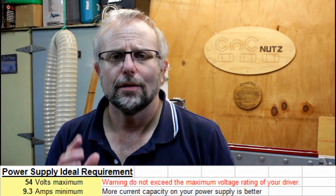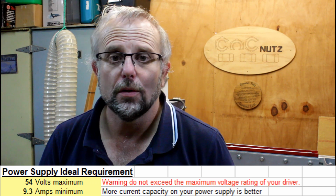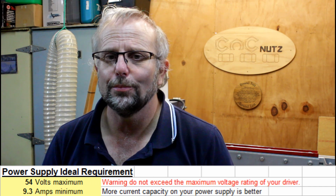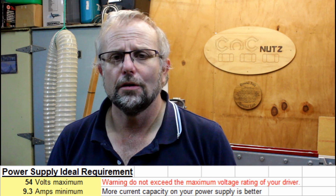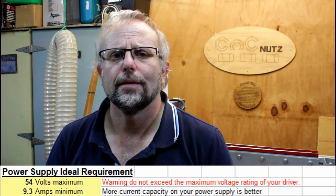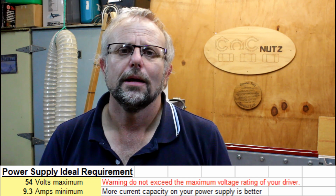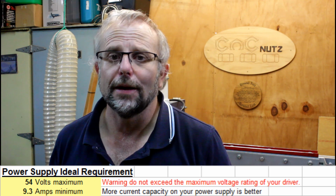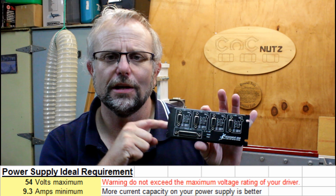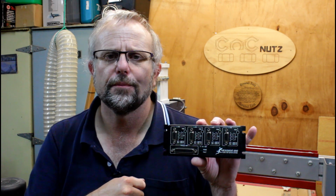Now the maximum voltage that the spreadsheet calculates is 54 volts, and that is a maximum. It doesn't mean you have to have a supply with that much, but the closer you get to it, the better it's going to work. So I did put a note there saying beware, make sure you don't exceed the maximum voltage rating of your driver, and that's important here because this can only be fed with 50 volts or less. If I exceed 50 volts, I'll damage the drive.